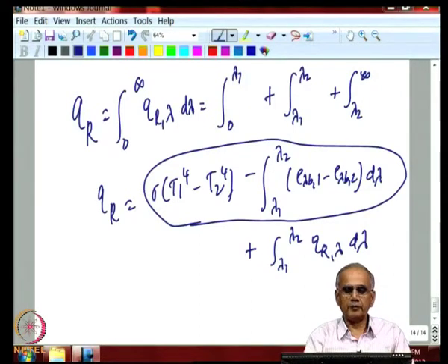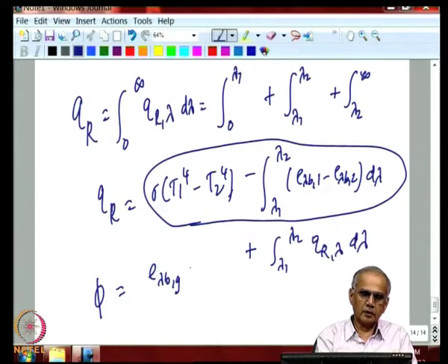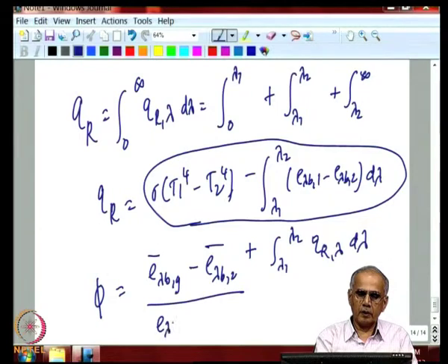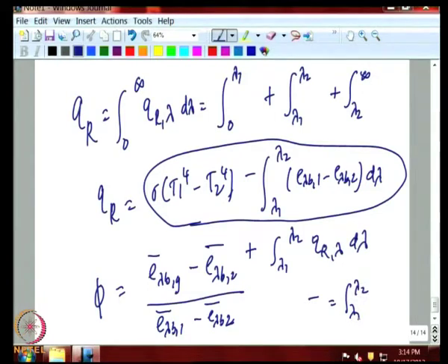So, now for this problem we define the non-dimensional temperature somewhat differently, because non-gray gas. We take the temperature of the gas in the wavelength range of interest to us, that is lambda 1 and lambda 2, and these bars are averages over the wavelength in which gas absorbs radiation.